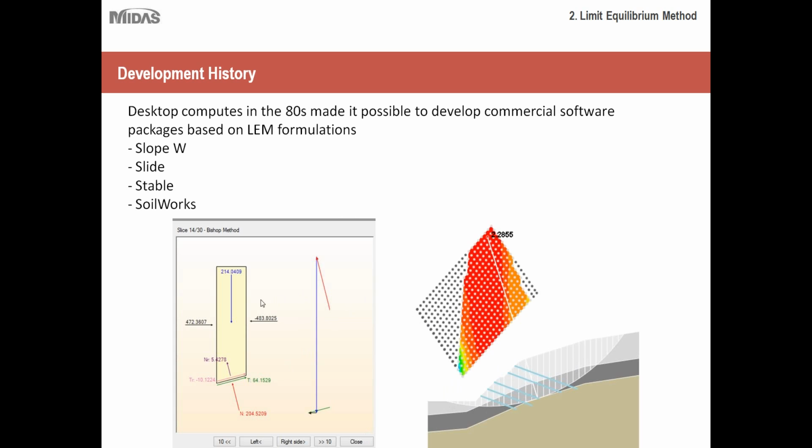And in fact, you don't even have to calculate the interslice forces or the forces acting on your slices by yourself. A computer program will do all of that for you. So it'll create a series of arctangents, and it'll perform the analysis over and over again based on this grid range. It'll isolate the minimum factor of safety for you. So something that would have taken half a day or maybe even 2 days for one engineer to do can actually be done within a matter of minutes by this computer program.